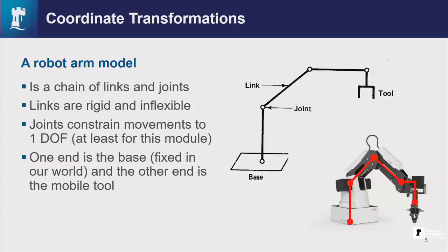So this is a real robot, the same configuration as this. Joint in the base, shoulder, elbow, and then there's one at the end. The configuration of this robot is a bit odd, as in this end piece will always remain parallel to the ground as the three major joints move around. It's called a palletizer type robot, and it's really for moving wooden pallets around and stacking them.